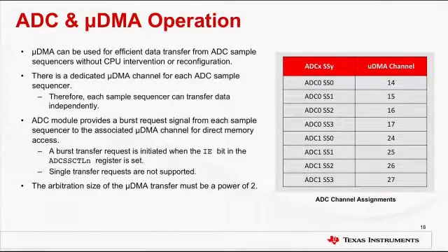The ADC modules in TM4C123X microcontrollers also feature 8 dedicated micro-DMA channels for ADC sample sequencers. Micro-DMA can be used to effectively transfer data from ADC sample sequencers without CPU intervention or reconfiguration.